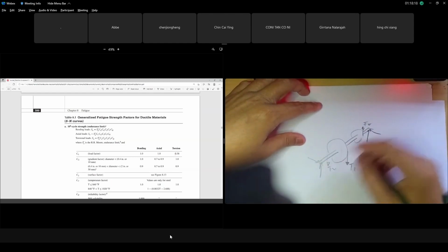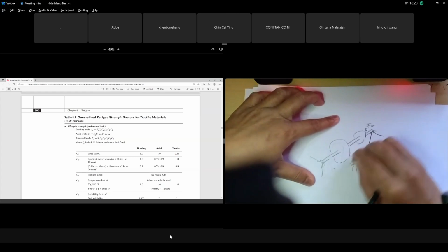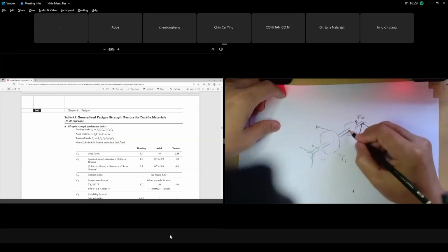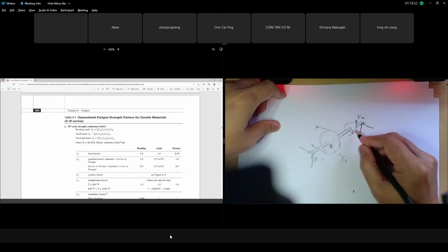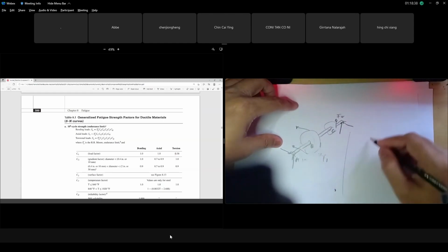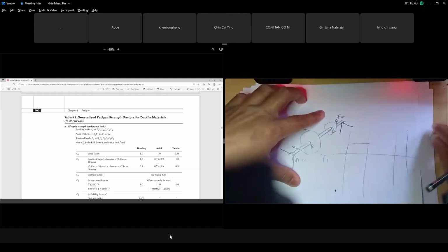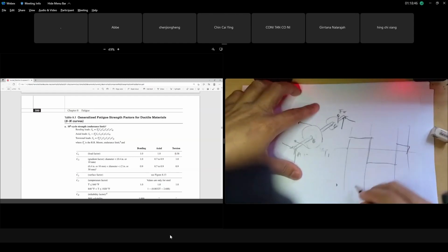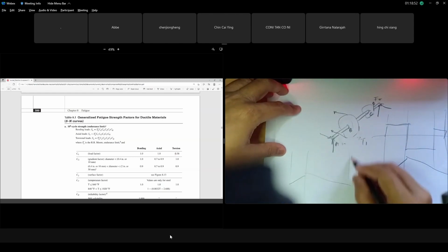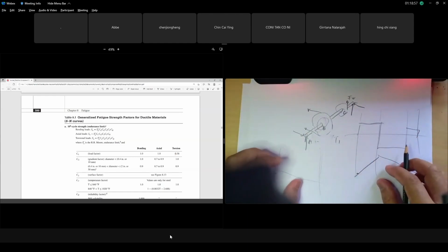Okay? And you have something like this, XY plane. Maybe your T1, T2 is not in this direction, can go in that direction. You have two planes. You have to consider two planes, XZ and XY plane. You understand what I'm talking about, guys? Along your A, B, C, along your B and C, which one is critical? Say B is critical. Remember you draw the shear diagram, right? Shear diagram like that, so you have something like this. Then you have a V like that, and then at the XY plane you have another moment like that. You found out B is critical, combining both planes.